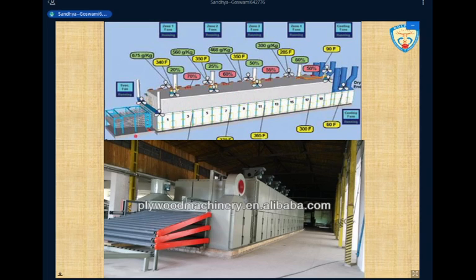This end that you are seeing, we call the wet end, where you can put your wet veneers; or if they are dried, then you can start from here. It is the dry end, right? Now, if you have cold pressed plywood, you will send it from here. At every step you can see chambers: 1, 2, 3, 4, 5, 6, 7.